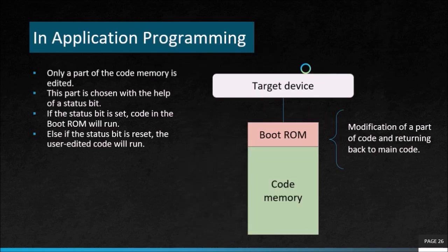The final approach I'm going to discuss with you is IAP, or In-Application Programming. This approach of integration is similar to ISP, but here we as users can control some part of the code. There's a status bit which, when set, runs the code in boot memory and which, when reset, runs the user-edited part of code.